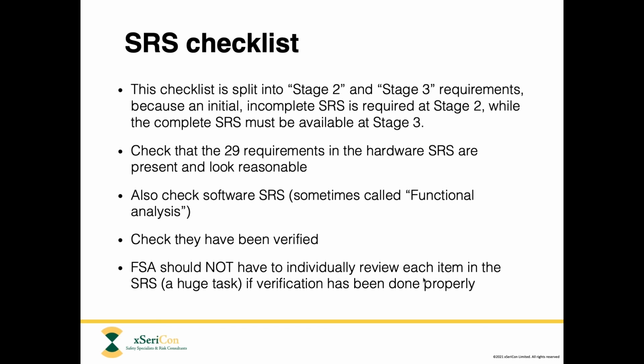Now, so far, we've only talked about the hardware SRS, that is the SRS that defines the requirements for the SIS hardware. But there is also a requirement for a software SRS, which is sometimes referred to as a functional analysis document. And this document is quite often prepared by the system integrator or by the vendor of the logic solver that's been used in the SIS. So that we also need to see and to confirm that it's meeting the requirements of the standard. We would like to see that the SRS, both hardware and software, have been verified.